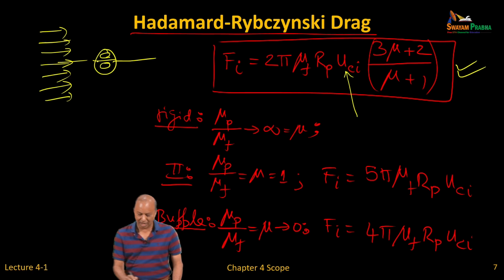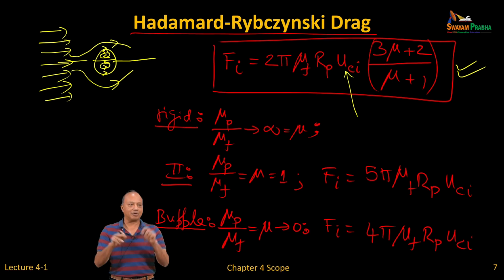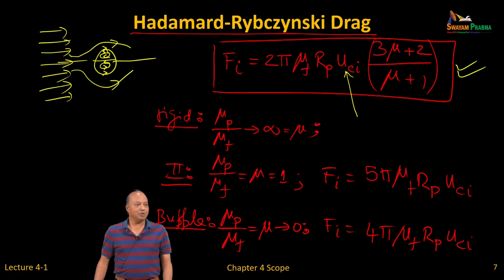Okay, so as the flow goes around it, there will be flow circulation inside the droplet. So there will be fluid going round and round, and therefore this outside flow is not being asked to be no slip. It cannot penetrate. We still assume a spherical droplet. So this problem also can be solved, a little bit more complicated.